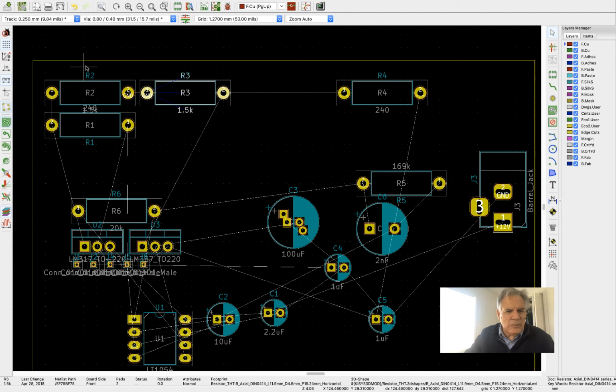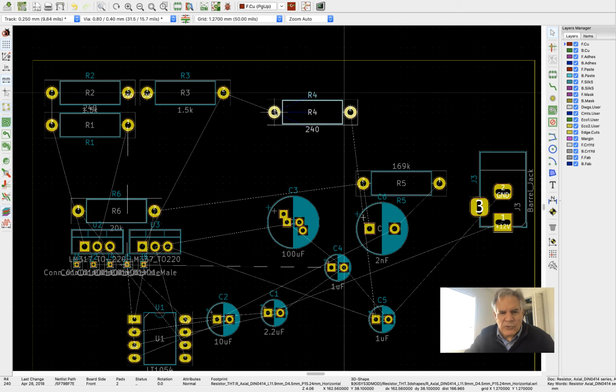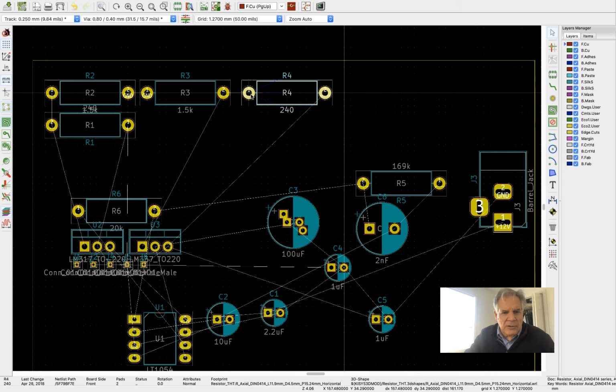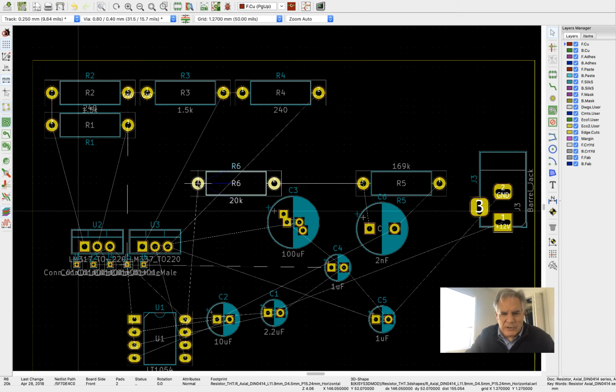And we don't want to push things right up to the edge. There are some design rules about how close to the edge you can come, and we'll be doing another design rule check essentially to see how that all goes. I'm going to leave this thing here for now. We've obviously got to figure out some other stuff here.